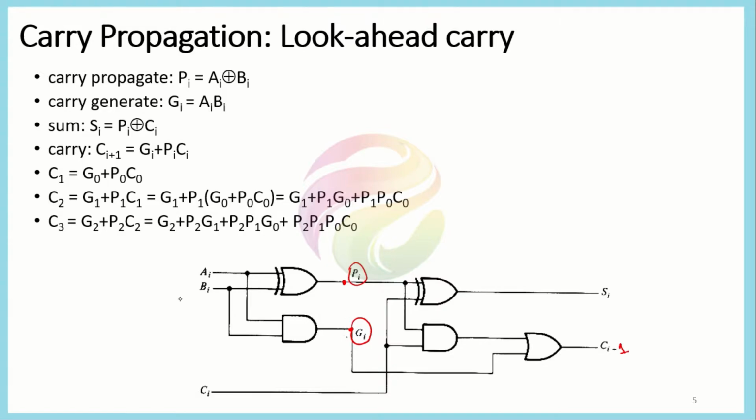So we have here Ai, Bi, and Ci. The subscript i represents the bit number, just like we did in the example. So it represents, say, the A0 bit or the A1 bit, the appropriate level. Similarly, this represents the sum bit Si, and Ci plus 1 represents the next carry that would be generated for the next cascaded full adder. If you write the equations of all these terms, they are very simple, because Pi is just the exclusive OR.